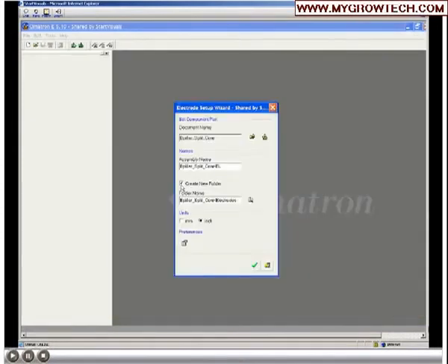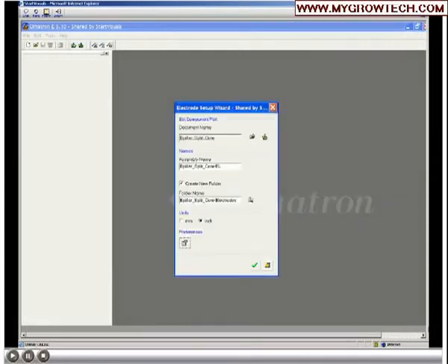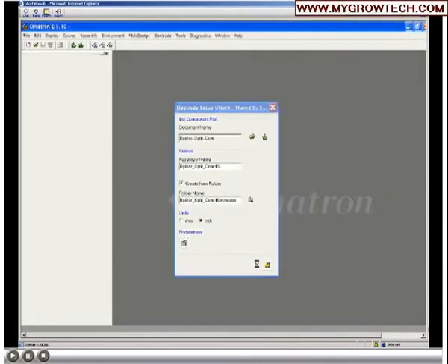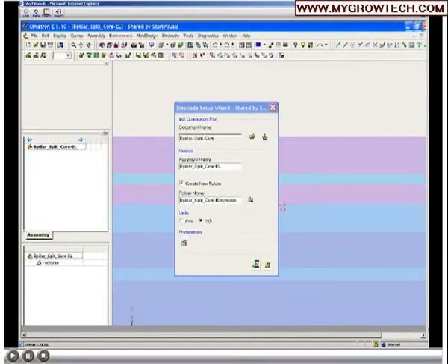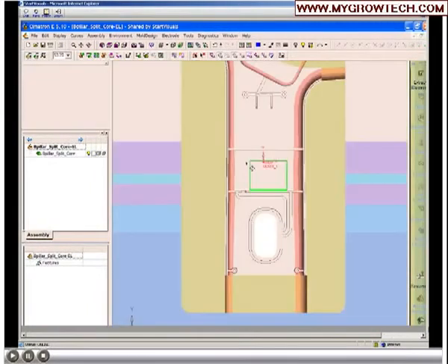I'm going to take a simple core or insert out of a mold. And something to look at just briefly is the ability to set up standards, such as how much do I want the graphite to green tip, or the overall graphite size, how much clearance do I want to have extended beyond the top mold surface, how do I want my drawings to look. All this can be standardized ahead of time for the electrode making process. Of course, with each job you may have unique needs, and that can be accommodated as we go through manufacturing it.